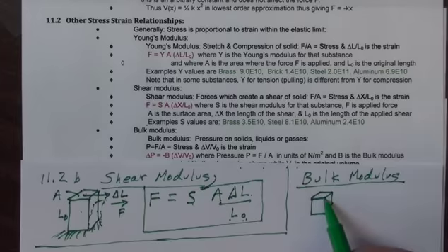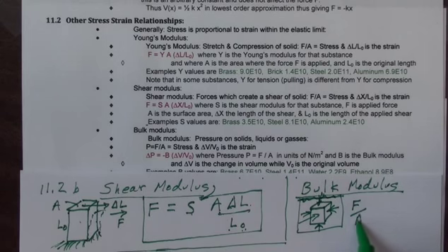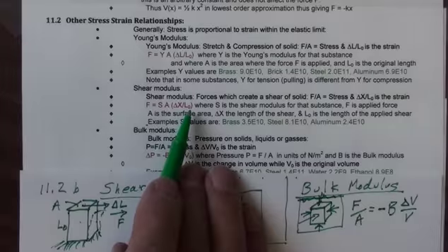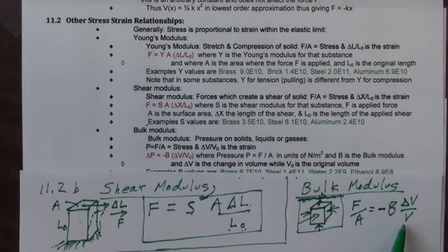The pressure is going to be the force per unit area, and it turns out that the force per unit area, or pressure, is going to equal, because the system always compresses, so there's a minus sign, times the bulk modulus times the change in volume over the volume. Just like before, we had the change in length over the length. Now we have the change in volume over the volume. So the fractional change in the volume of the system, you notice that this is dimensionless. Each of these is dimensionless. That's length divided by length, volume divided by volume.